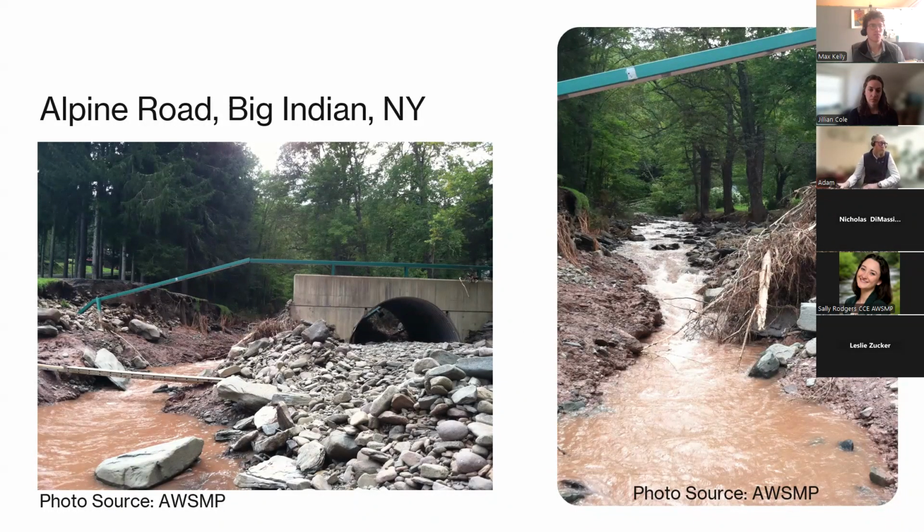Once that plugged with debris, since it couldn't adequately convey the wooden material that was coming downstream, it led to this kind of drastic failure and avulsion where the stream just cut directly around the culvert.